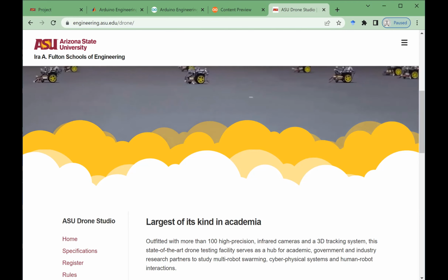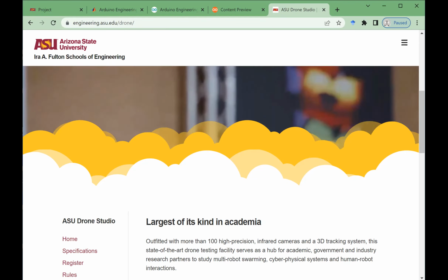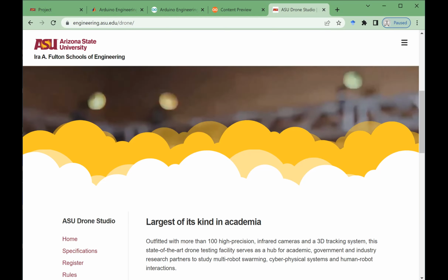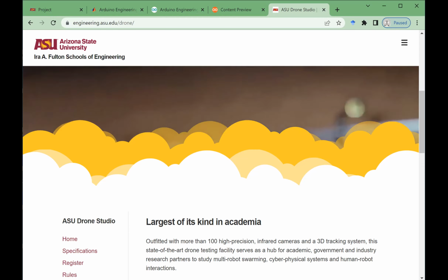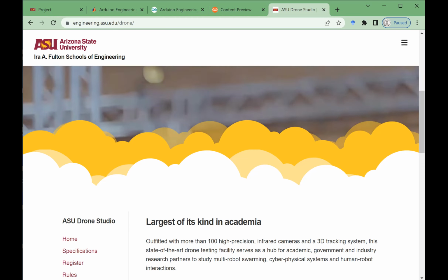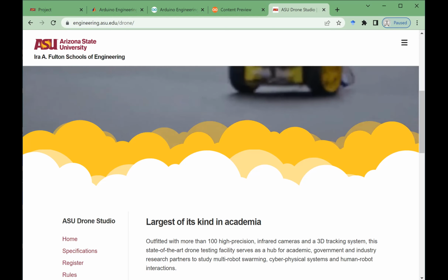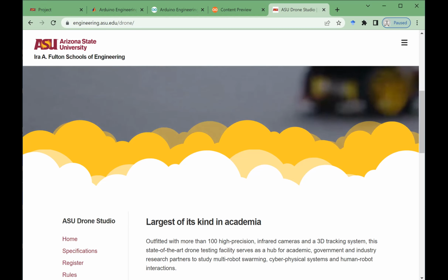So the first two robots, you need some space for testing. There are additional things that you can do, and I'm not going to recommend that to undergraduate students, but for grad students, if you want to integrate the motion capture with the motion of the robot, you can do that. For example, the robot would have motion capture dots, and the OptiTrack system can actually do the triangulation and tell you where the robot is.